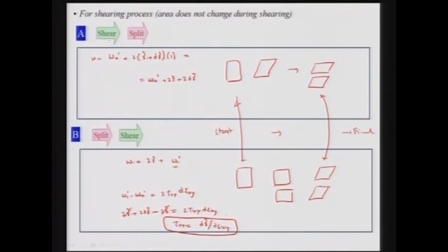We can see in a similar fashion that this term does not appear for the liquid. So again for solids, the shearing stress is basically dependent on the change in the surface tension due to the shearing strains, that is basically changing the overall surface energy of the system. So the surface energy is not equivalent to surface tension in the case of solids, and the surface shearing stress is also doing some work in the case of solids.